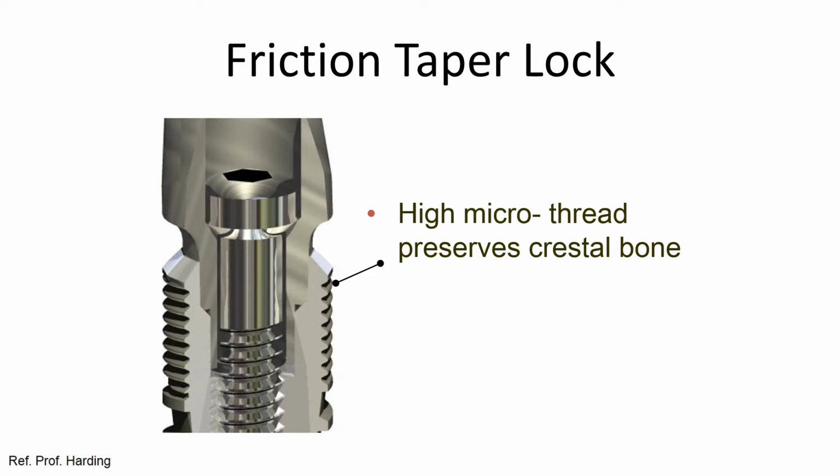So we can see here that the wall thickness in this area here is quite thin, and this is our abutment, and this is the depth of our thread here. So we can see here that there is a very small amount of metal, and this would be a weak area and a potential area for implant fracture.